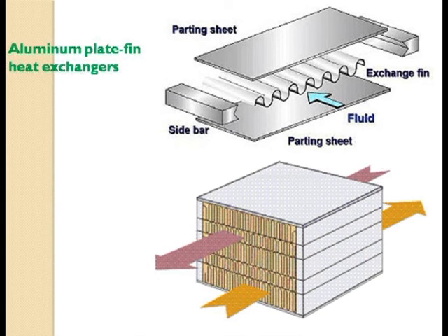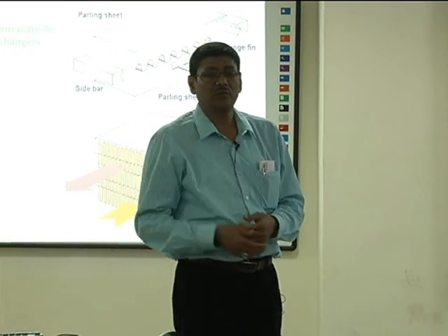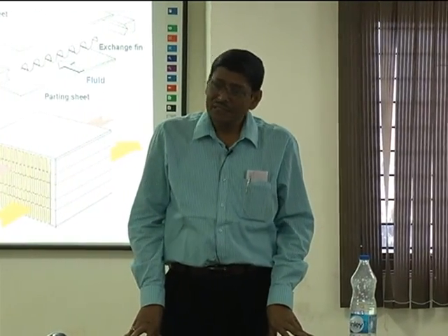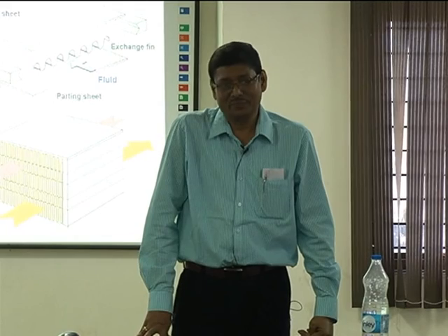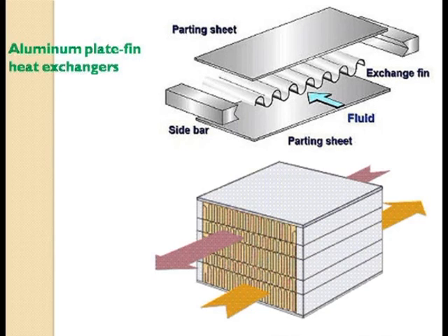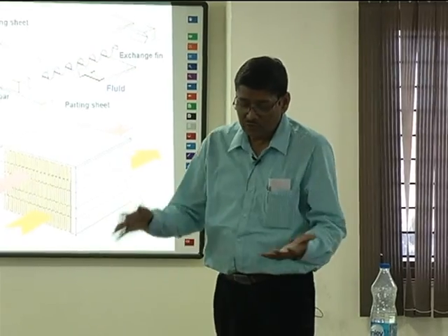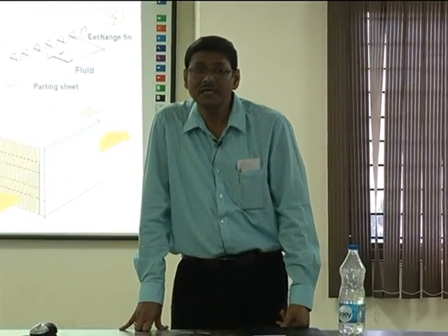Now you can arrange this in other directions also, so that it becomes a cross flow type, and you can have a multi fluid, multi stream heat exchanger, and this is what is shown here in a combined unit. This is really very efficient from the point of view of large applications and large size heat exchangers. They are compact, have high effectiveness and low pressure drop, everything required for large size plants. They are slowly replacing all types of shell and tube and coil tube heat exchangers, because manufacturing technology has come up so nicely and is so mature now. We are easily able to manufacture these heat exchangers, they occupy less space, which is the major advantage, and performance is still higher than the other heat exchangers.